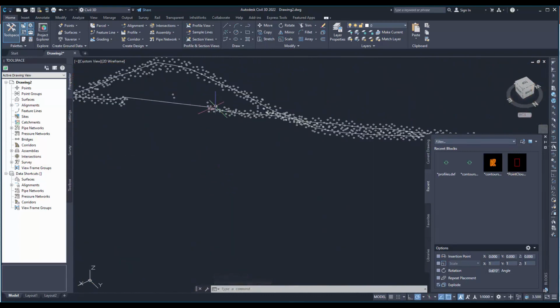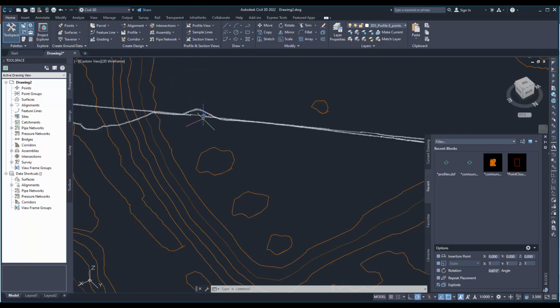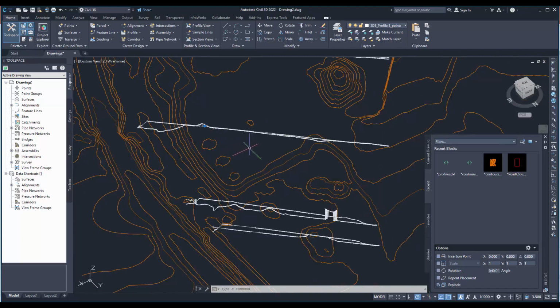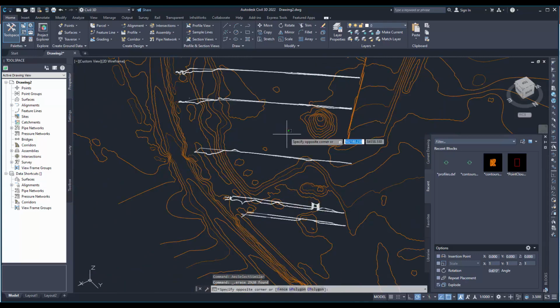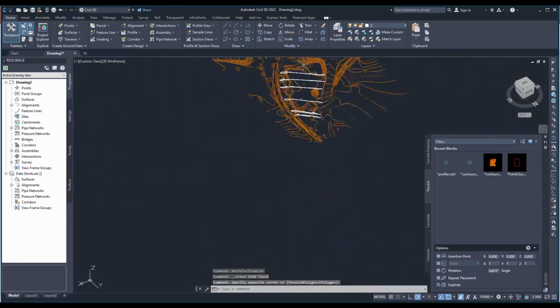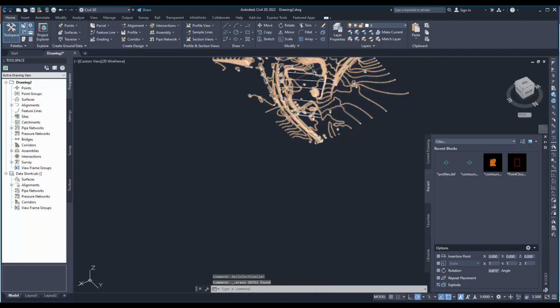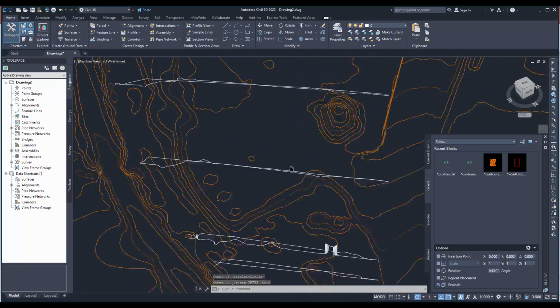One thing I actually recommend you to do is, here you see, so with the profiles we also export the points which were used to define the profile. Oh, these aren't strictly necessary. We can use this one, select similar, to select all of them, and then just press delete. We'll do that on all the cross sections right now, like that. Left select, select similar, delete. Now we should be left with the profiles only. Perfect.